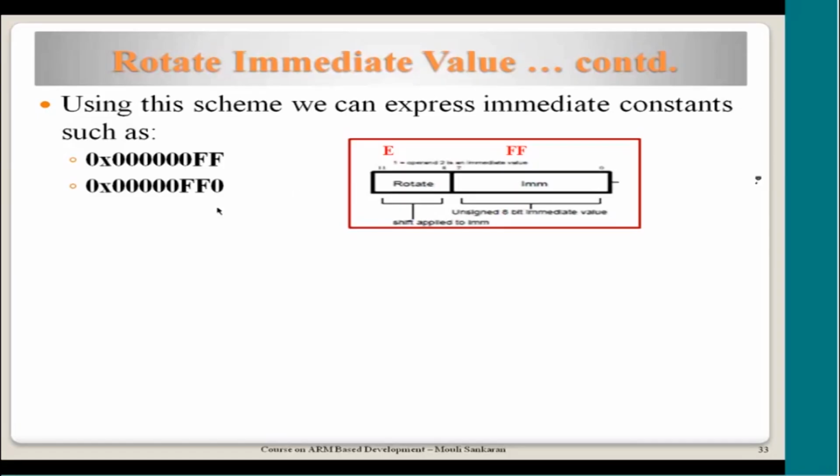So what the ARM assembler has done is it has effectively allowed you to mention this pattern with the restriction that only 12 bits are allowed for the constant. So all patterns cannot be given, but some patterns can be, and it is able to do this. Now you may wonder, instead of FF, can I give something else? Yes, of course. From 00 to FF you can give. Only thing is it should be a byte value. Any pattern you have should not be more than a byte. It can sit anywhere because you have flexibility here.